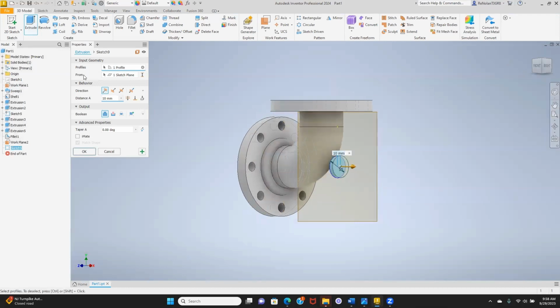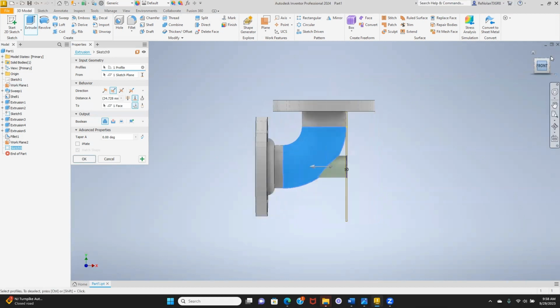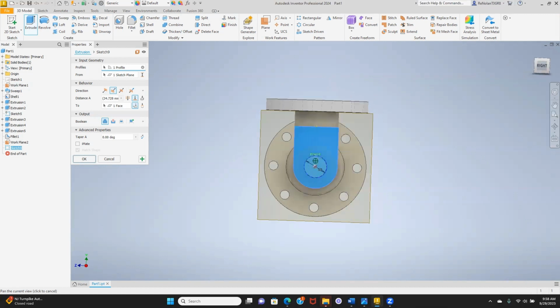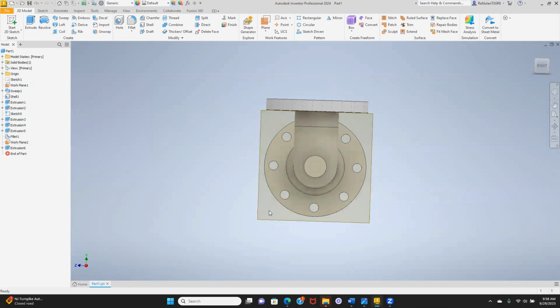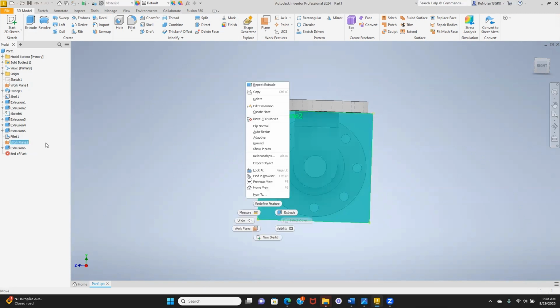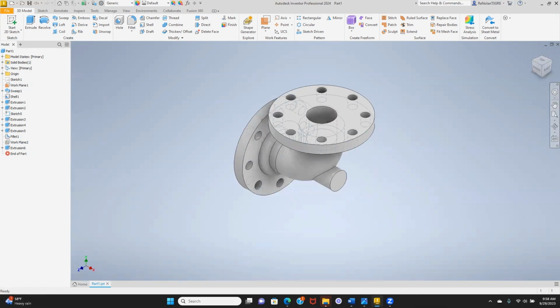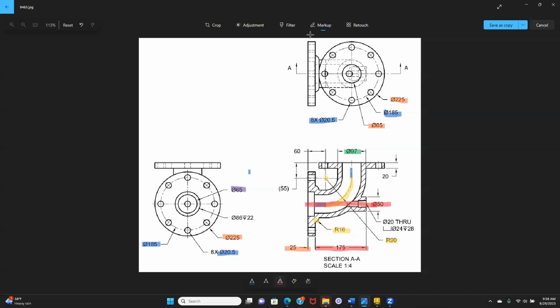We're going to select that face and we're going to extrude to another face, in this case that face being the pipe. This is a great way to get a full connection along a curve. If you extruded a distance, we might have either not hit the pipe completely or gone into that hollow area. This is a great way to secure that connection. Now I'm going to go in and hide this plane just to make things more professional and easier to see using that visibility option.